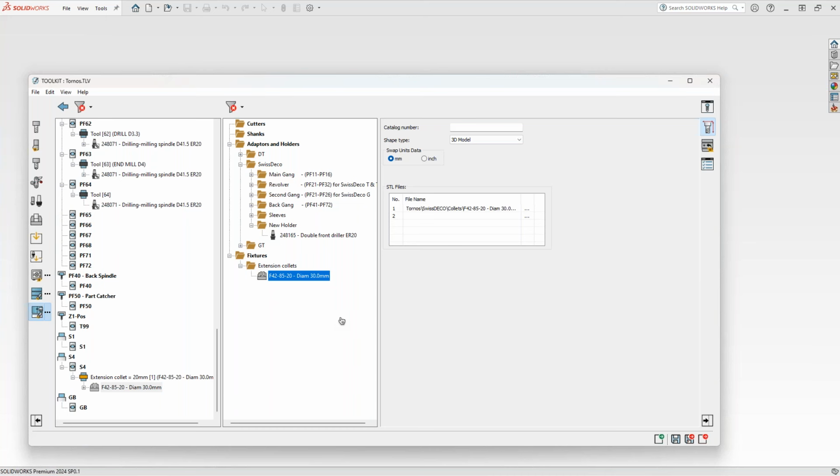So now for the first time, you can also go from the higher level of library to the lower level of library. And the benefit of doing it in this way is that you are not losing time. If you need to define something inside the vault, you need to close your project, do it there, then open the project. But you can actually continue defining any of your components on the part level, and then later you can just pull it out into your library anytime when it's more convenient to you.